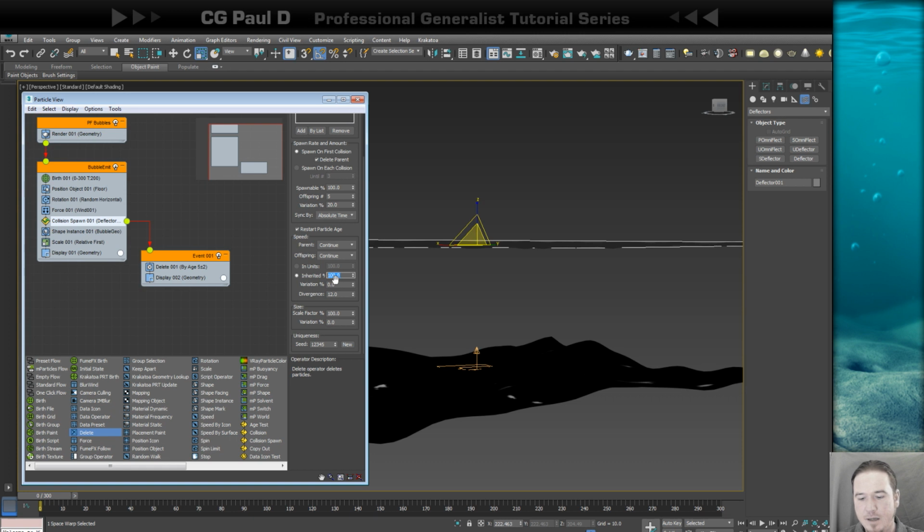So we're going to drop it down a little bit, to 65 with a variation of 15. And then I want to do divergence 90 degrees, because currently our bubble's facing straight up, so the angle's straight up. Now I want to make sure it's a little mini explosion that comes out and fills the whole angle from the straight angle here to 90 degrees, which then happens all the way around 360. I hope that makes sense.